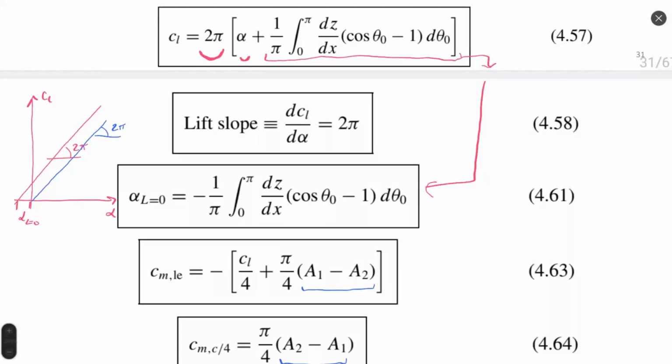We continue today to talk about incompressible flow over airfoils, and last time we elaborated two methods: calculation of symmetric airfoil and calculation of cambered airfoil, not symmetric. For symmetric airfoil, it was simple that lift coefficient was CL equal to 2 pi multiplied by alpha, a linear function.